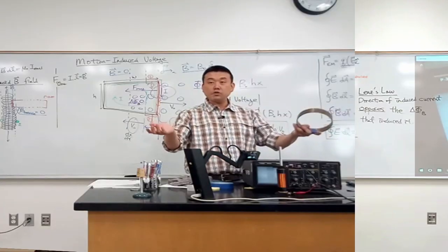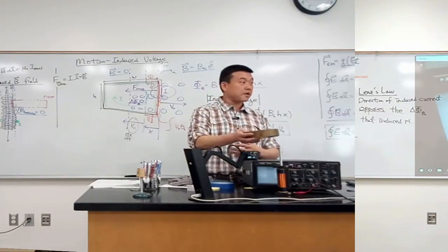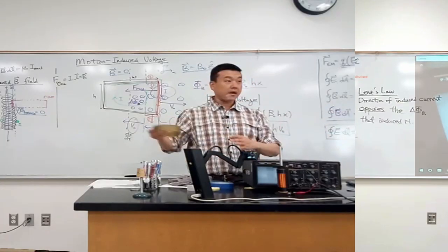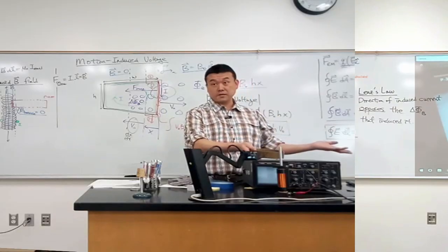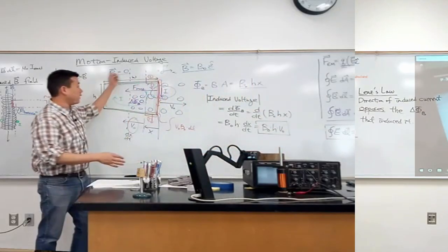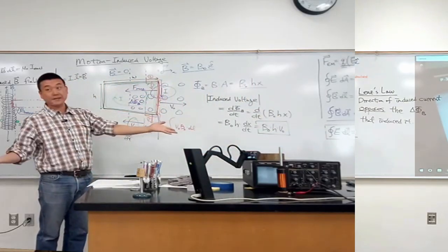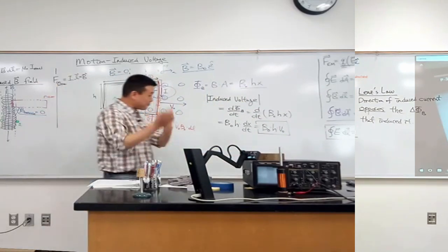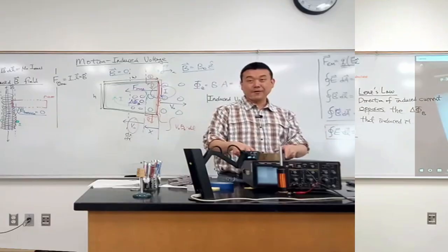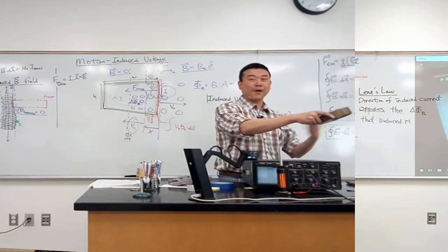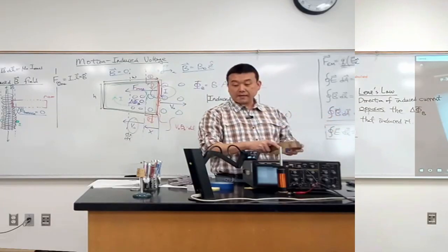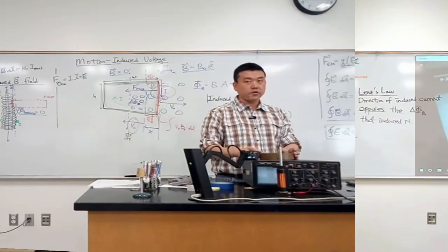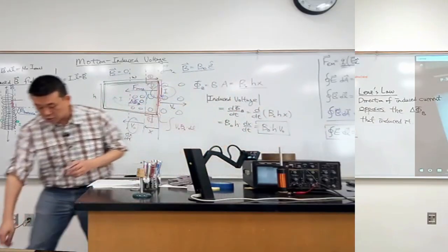And your intuition says that if something slows down to a stop, you can understand it, right? Mechanical energy went into some thermal energy. In fact, if you have a current flowing, it has resistance, you're going to get Joule heating. So it makes sense that you're going to lose mechanical energy. The other picture is just an absurdity, where if it just takes off, where is that energy coming from? And this is the way that you can understand something called eddy current.